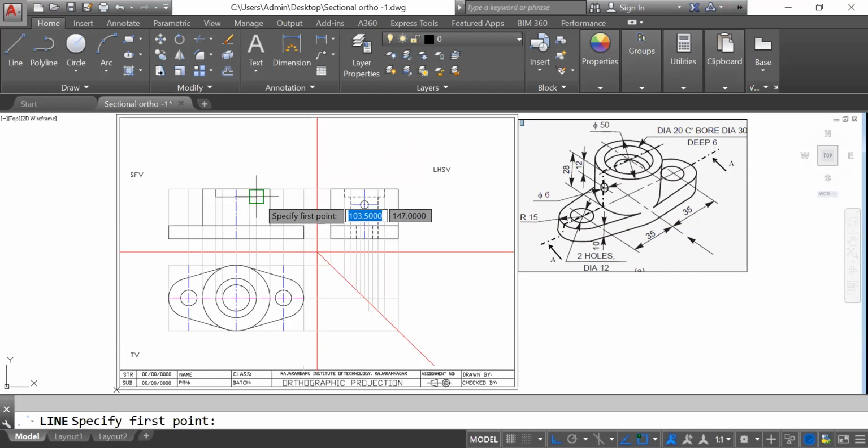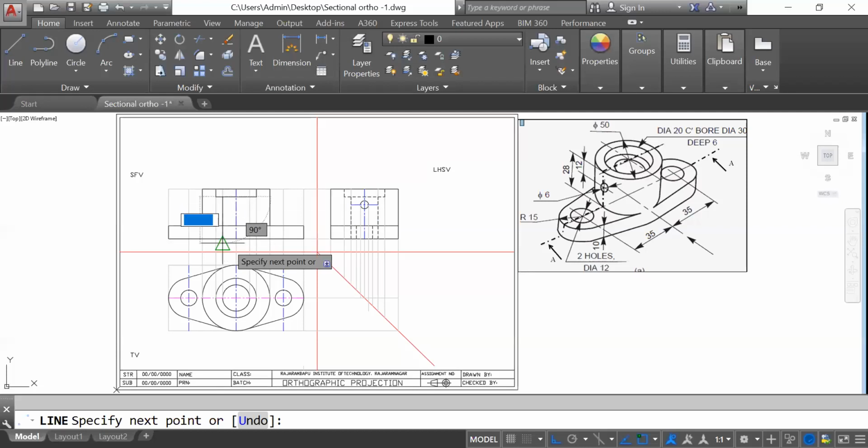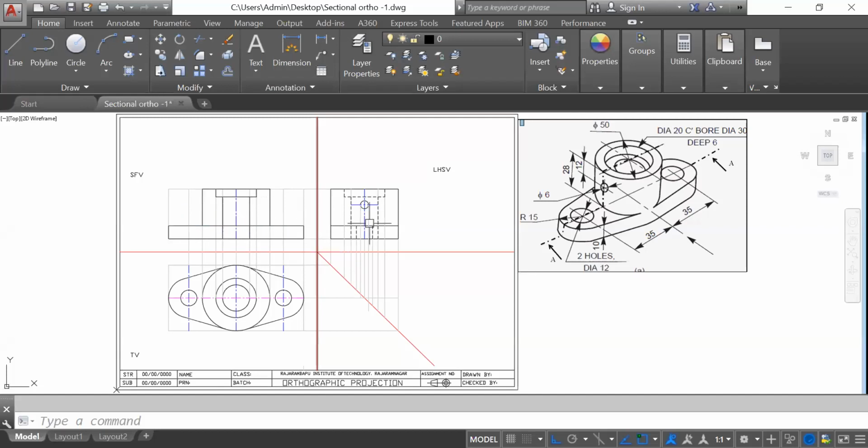Okay. Then there would be 20 mm depth. So this circle, 20 mm hole with depth full throughout. Okay, so it would look like this. But if you consider this part, this T section is a hidden line, as like this in the side view before cutting. But when we take a cut, that would be clearly visible. Getting? That would be clearly visible. That's why we have to show it by visible lines. Okay, so when we take a cut, what happens is that it would be visible clearly.